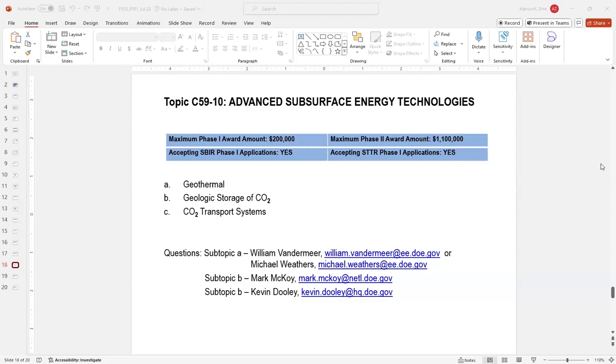So in terms of critical metrics, we're looking for hardening the permanent sensor arrays to last at least 5 years and perhaps up to 30 years. Design permanently installed arrays where data may be collected automatically and unattended. Design a field acquisition to provide good sensitivity in the injection zone, which could be at depths greater than 2,600 feet below the ground surface, and also be able to monitor changes at the boundary of the CO2 plume for